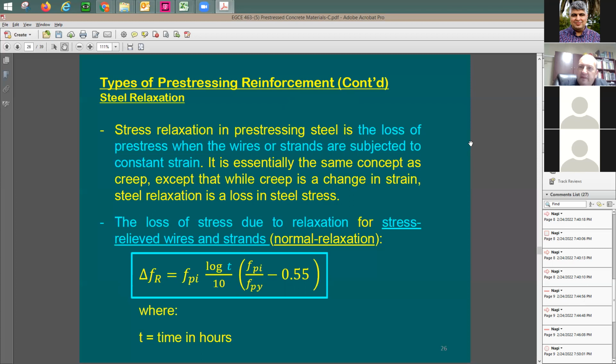Relaxation. How can you figure out the relaxation? What does it mean by relaxation here? You take the rebar or the strand or the wire, any one of them, you apply tension to it. I'm sure that you're going to have extension, right? Once you apply the tension force, you're going to have elongation. And then you leave it there. You leave it for a month. You leave it for a year. The amount of strain that you put in there in the rebar is going to get less and less and less. And this is also going to be part of the 20%, the losses.